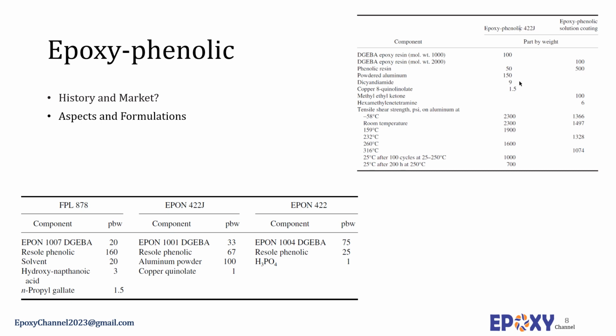Commercial epoxy phenolic adhesive formulations generally contain more phenolic resins than epoxy resins, and as a result, they have good high temperature and chemical resistance properties. But the adhesive suffers from relatively poor peel and impact strengths. Their resistance to weathering, oil, solvent, and moisture is very good. However, because of the rigid nature of the constituent materials, epoxy phenolic adhesives have relatively low peel and impact strength and limited thermal shock resistance.